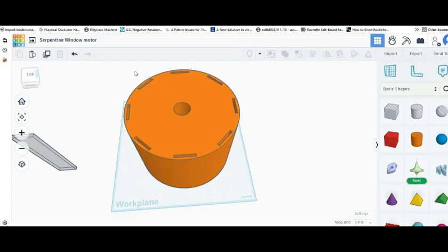The other thing that does for you is once you have a 360 coil out around here, where do you put your Hall effect in order to get the timing? I mean, you could try and put it above there, but that's not where it's supposed to go. So you would want the Hall effect out here, except for the coils out there all the way around. So you extend this up, you put in some more magnets that are aligned with these, and that's where you have your generator coils, and that's where you have your Hall effect. So there's still a lot to do, and let's just see what we can get done here.